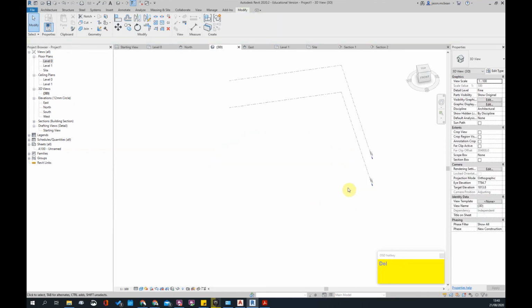I just meant when you're measuring the 6 meters before the landing, do you measure the 6 meters inside the arc or outside the arc, in the middle of the arc? Yeah, so generally you want the inside of the arc because that's going to be the most extreme angle.